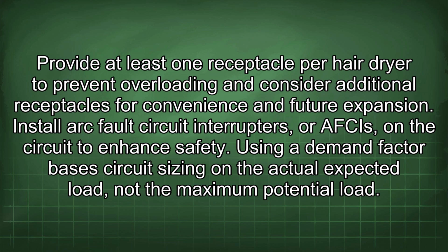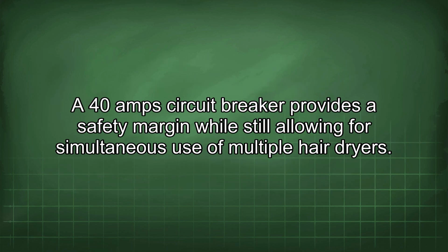Using a demand factor bases circuit sizing on the actual expected load, not the maximum potential load. A 40 amp circuit breaker provides a safety margin while still allowing for simultaneous use of multiple hairdryers.